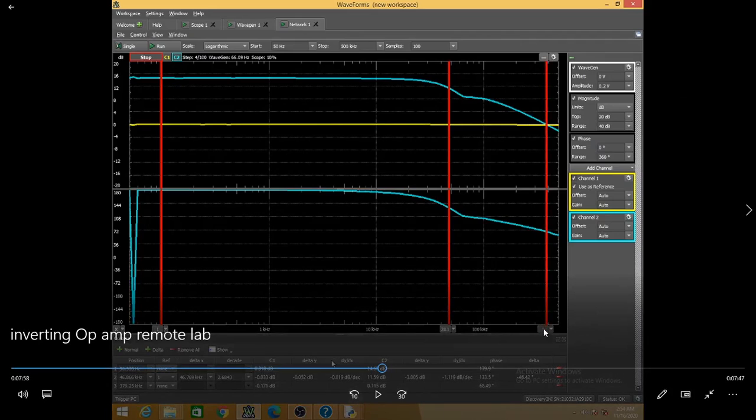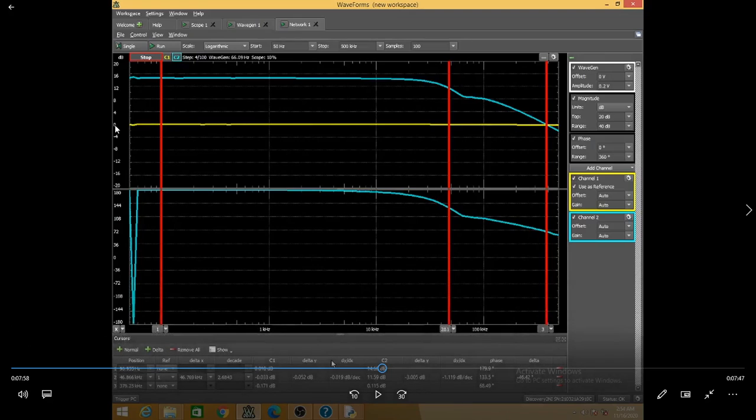What I'm trying to place here is the frequency corresponding to unity gain. Can you see this is 0 dB? Yes, sir. 0 dB corresponds to 20 log of 1, which is 0, no? Whatever is inside the log, 1, is nothing but the gain. What is the gain then? Gain is 1, no?